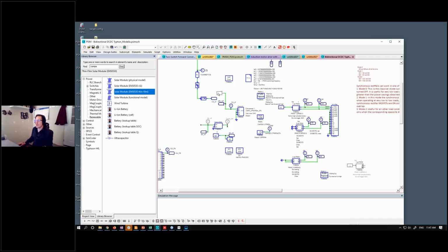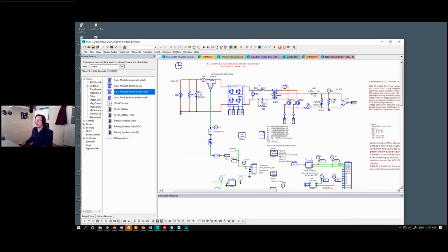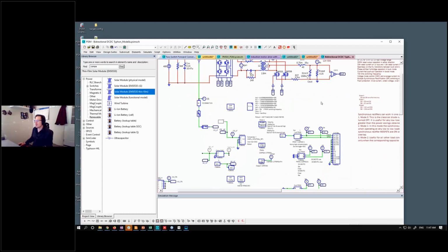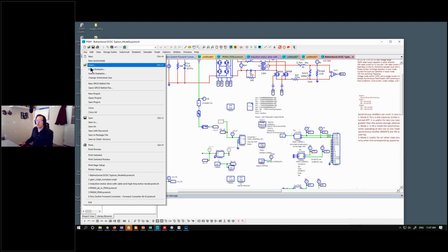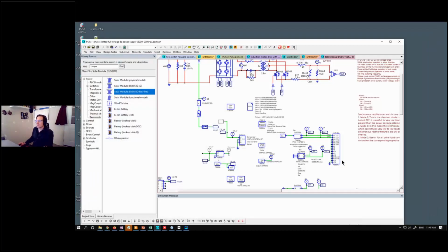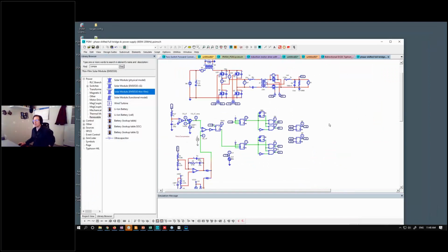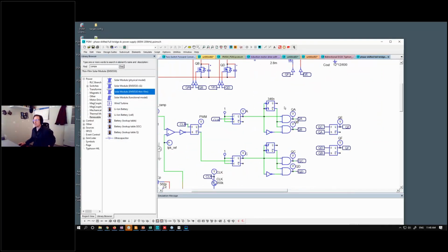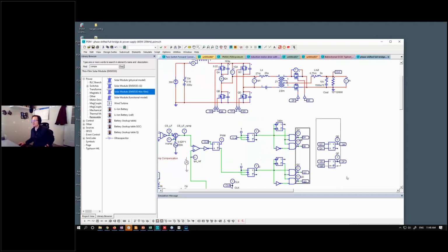So this is also looking at the XBAR support. This is running peak current mode control, and we're using a comparator trigger signal to shift the phase shift on this. And then we've got the active secondary being generated from the control signal. So that is the equivalent of code generation of something that looks like this, which is a little easier to visualize than the XBAR implementation, but we've got the primary side switches generating what the secondary side switches will be for the active rectification.